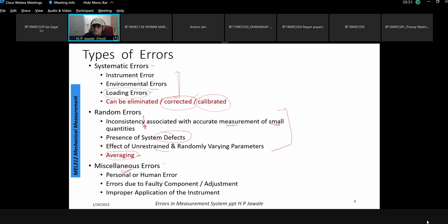The same is the case with angle measurement, where there is some workpiece or job on which the angle is to be measured. Say, for example, temperature measurement, or pressure measurement. The instrument selected might be an improper instrument. For the measurement of say 1 bar pressure, if you are using an instrument with a very large scale range, suppose 100 bar or 200 bar, and you use it for measuring 0.5 bar, possibly the instrument is not designed to take care of that 0.5 bar pressure.